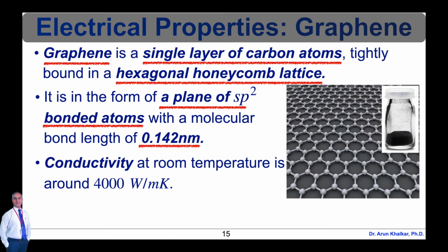Graphene is the thinnest compound known to man at 1 atom thick, and the lightest material known, with 1 square meter weighing around 0.77 milligrams. It is the strongest compound discovered, between 100 to 300 times stronger than steel, with a tensile strength of 130 gigapascal and Young's modulus of 1 terapascal.